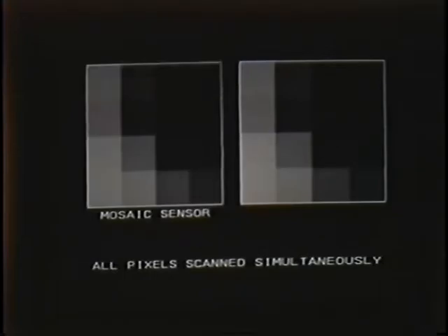The type of sensor that produces images like these is known as a mosaic sensor. It is called this because the sensor actually consists of many detectors held together in a focal plane array. Each pixel in an image is the product of one of these detectors. The key element of a mosaic sensor is that each of the detectors, in a sense, takes a picture simultaneously. In other words, the 16 pixels in our blinking image here are all produced at the same time, as if they were 16 individual pictures. Each of these pictures are then put together, like a mosaic, to make up the image.